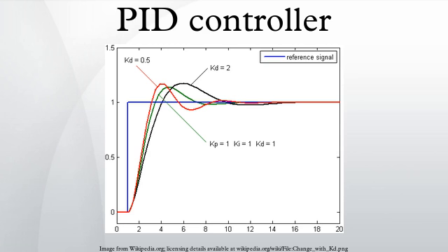Overview of methods. There are several methods for tuning a PID loop. The most effective methods generally involve the development of some form of process model, then choosing P, I, and D based on the dynamic model parameters. Manual tuning methods can be relatively inefficient, particularly if the loops have response times on the order of minutes or longer. The choice of method will depend largely on whether or not the loop can be taken offline for tuning, and on the response time of the system. If the system can be taken offline, the best tuning method often involves subjecting the system to a step change in input, measuring the output as a function of time, and using this response to determine the control parameters.